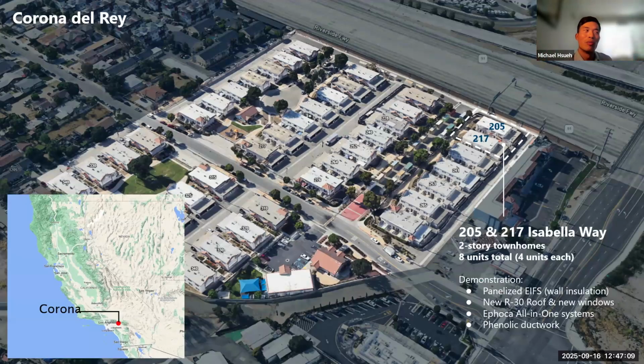The idea was that we had brought the attic fully into the thermal envelope, and we installed relative humidity sensors and did some hydrothermal modeling of that space to verify, and we checked with the sensor data that it was already very bone dry in that attic beforehand because it was vented, hot climate.